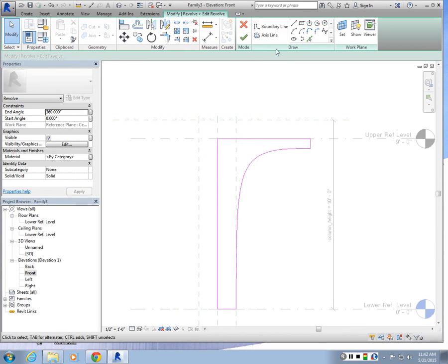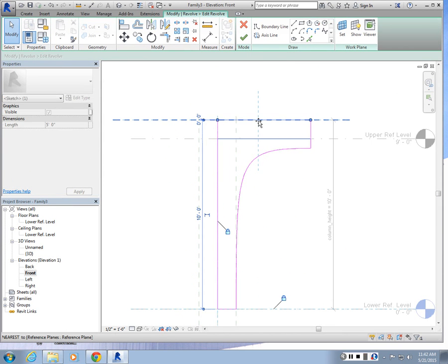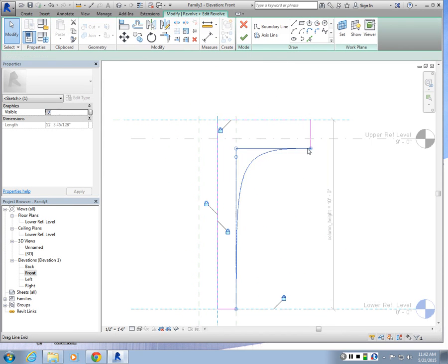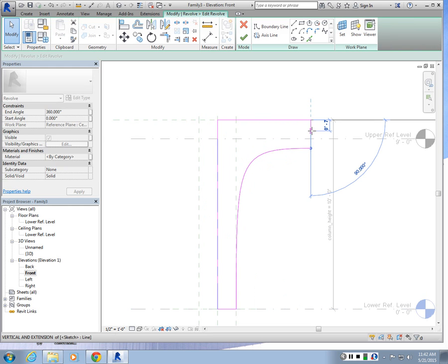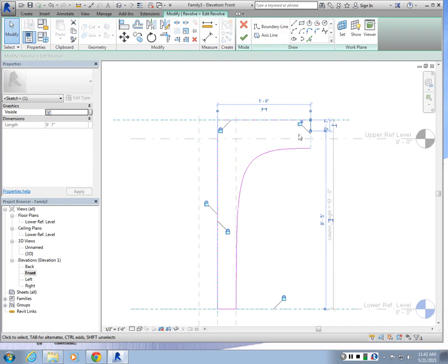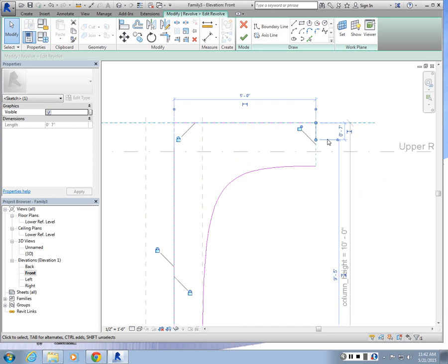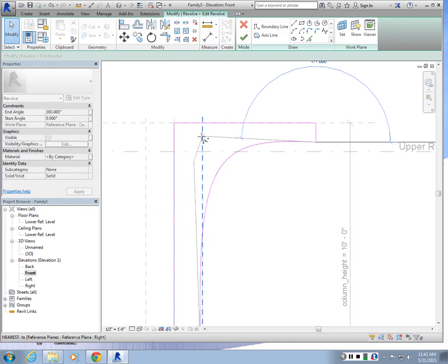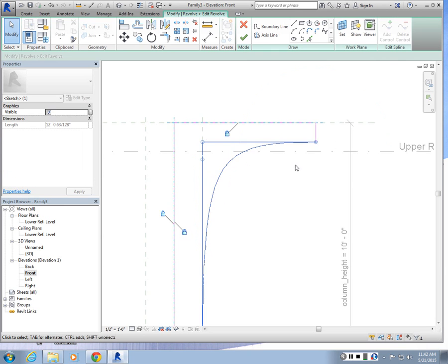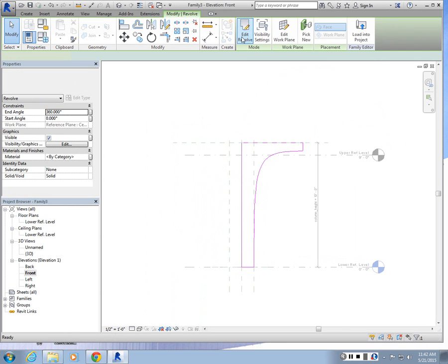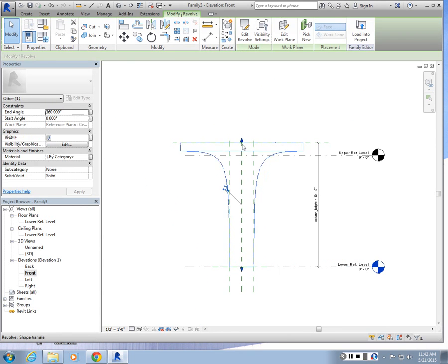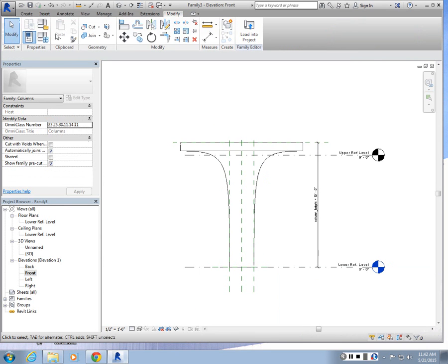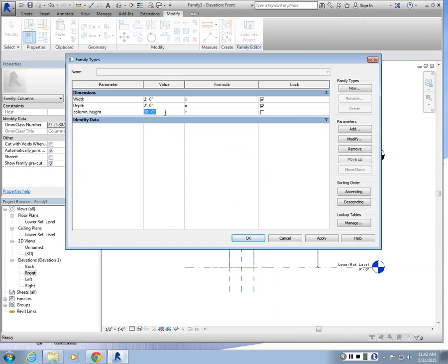Now if I go to edit revolve, I can snap to this reference plane. Pretty much similar stuff we have been doing, right? I can also create another offset plane here for that thickness. This guy, let's move it there. These guys, let's move it here. Hit check. Let's see if it's going to stretch. Otherwise, I may have to make it a bit more.